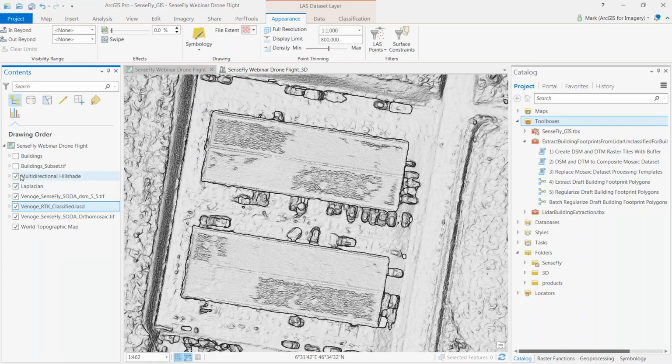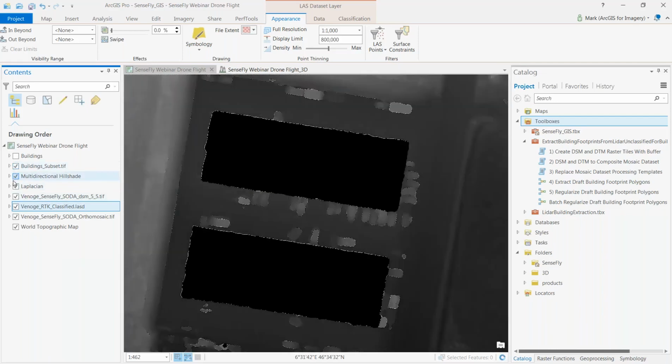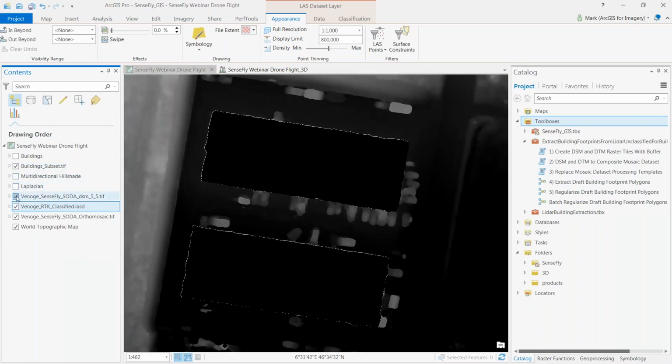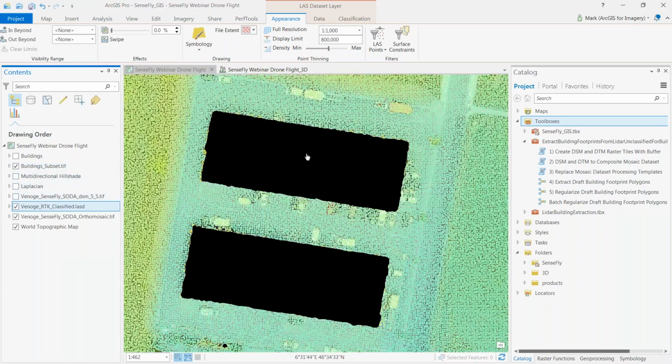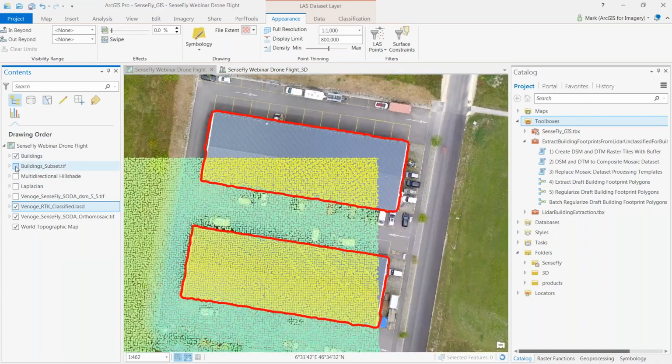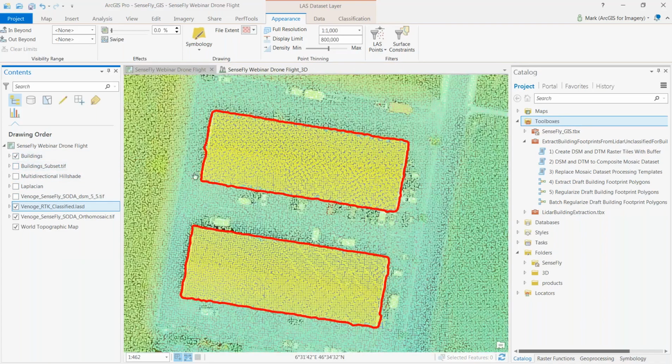And then once we have that, we can make a binary file that just basically has zeros and ones, the ones representing the outlines of the buildings and certain textures. And at the end, what we end up getting are some raster building footprints that we can then vectorize. And then what we get is kind of like a generic building footprint layer.